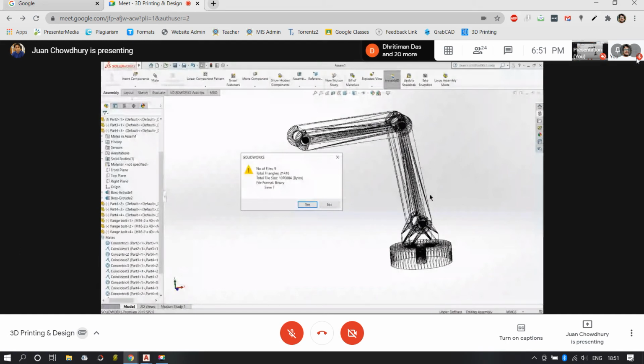Now the screws, if you remember, I have put in between, right? So there's nothing that's holding the screws in place. So while printing, it's exactly going to print it that way. It'll just create some webs for the structure to be printed, which you can later remove and still get the assembly rotating. All right, is this part clear then? Is the doubt resolved? Yes, sir. Okay, great. Thank you, sir. Anything else?